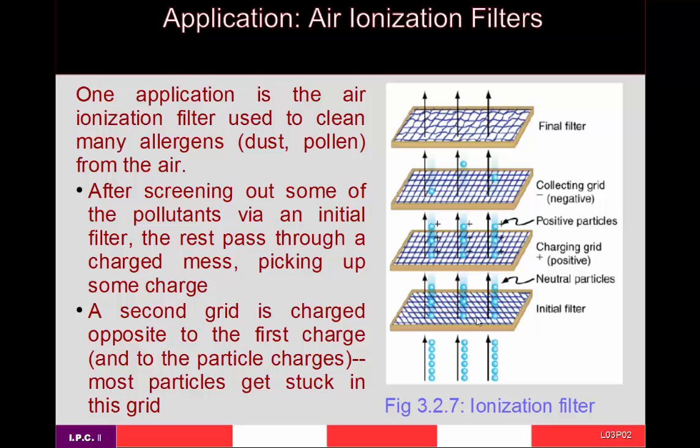But by removing 85%, you're still left with 15,000 particles per cubic meter. And what you really want is to have, say, 1,000 particles per cubic meter, or maybe 100 or 10. 10 is pretty dang good. That's a clean room in which you're doing silicon manufacturing and you have to put on a bunny suit to walk into the room.